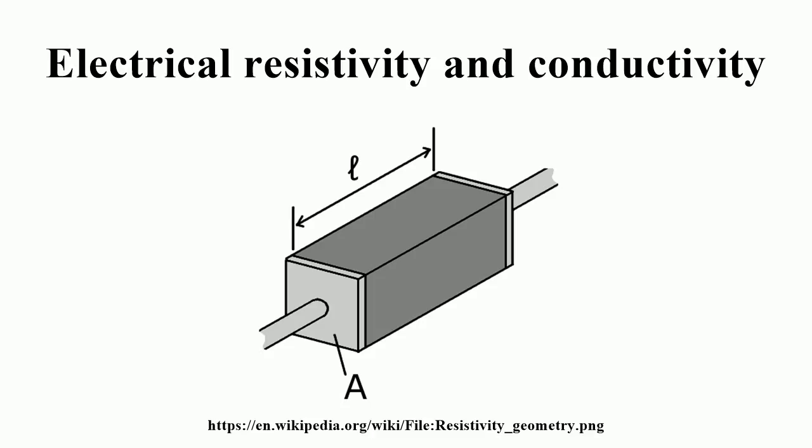In 1986, researchers discovered that some cuprate perovskite ceramic materials have a critical temperature above 90 K. Such a high transition temperature is theoretically impossible for a conventional superconductor, so the researchers named these conductors high-temperature superconductors. Liquid nitrogen boils at 77 K, facilitating many experiments and applications that are less practical at lower temperatures. In conventional superconductors, electrons are held together in pairs by an attraction mediated by lattice phonons.